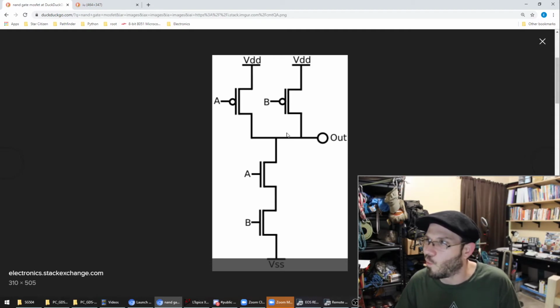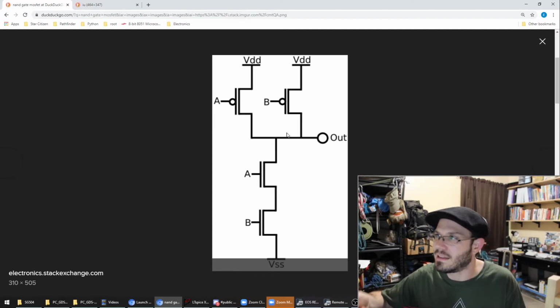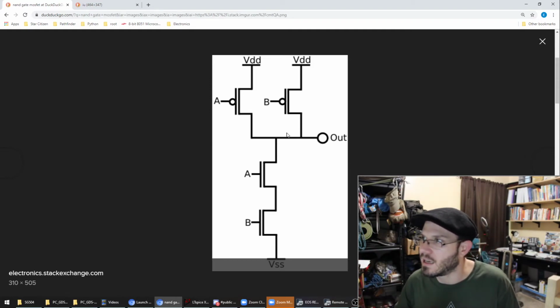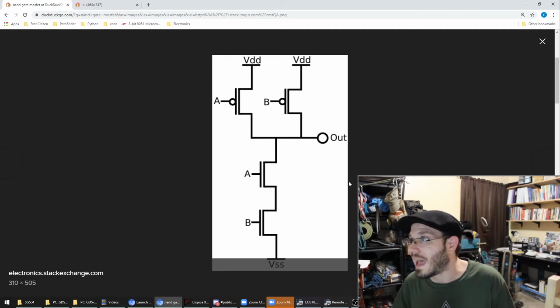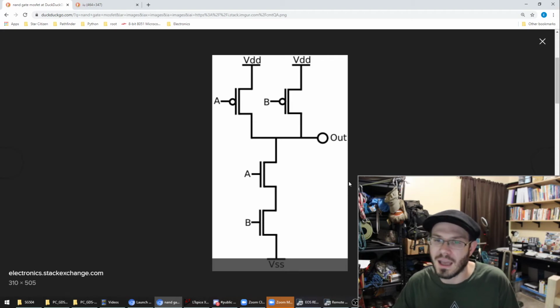But if you're synthesizing for a physical layout and constructing the actual MOSFETs on a piece of semiconductor to make an integrated circuit, then you want to use the least number of MOSFETs possible. So any type of synthesis should be able to reduce it down into that universal gate, or the fewest logic gates needed for your desired digital circuit.